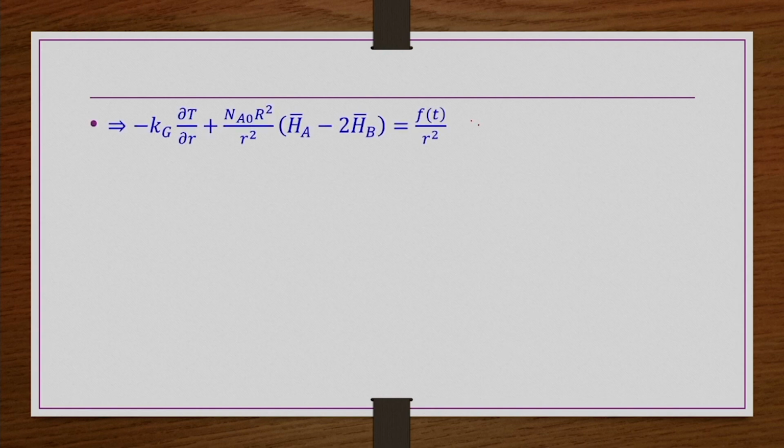That dividing we will do later. The same equation is given here now. Now, what do we do? We have to take some reference temperature in order to define these things. These H_A bar, H_B bar are usually defined with respect to some reference temperature, so that we can bring in C_PA bar, C_PB bar, delta T, etc., because C_PA, C_PB information are known for many of the cases in general, from the standard thermodynamic books.